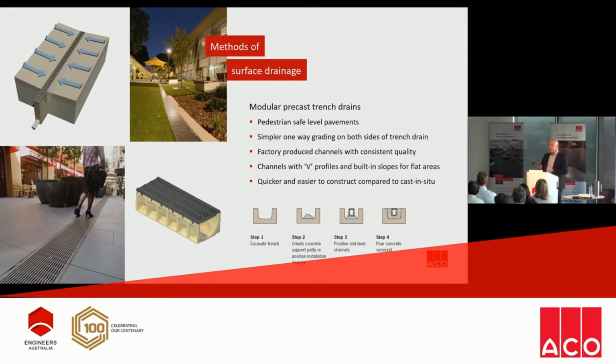Also, there's systems available in the market that have V-shaped profiles and built-in slopes for flat areas, so they do increase the velocity within the channel system. And I'll talk more about that during the presentation. And generally quicker and easier to construct compared to that of a cast in situ channel. So generally a precast system should be a 4-step process. So what that means is less installation cost at the back end of the project,